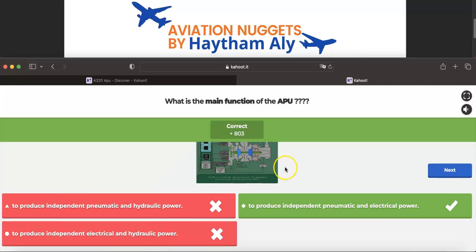So if you are asked anytime what the main three components that compose the auxiliary power unit are, you can clearly identify: we have a power section, a load compressor, and an accessory gearbox. The function of the power section is to produce mechanical shaft power to run the load compressor and the accessory gearbox. The load compressor provides the aircraft with bleed, and the accessory gearbox accommodates the AC generator that will provide the aircraft with electrical power.